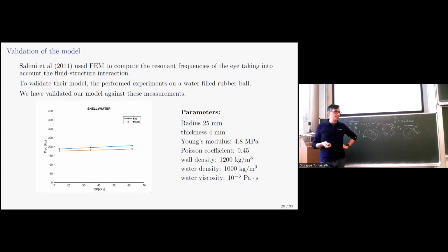And the reason for this discrepancy, I think, is because the Young modulus of rubber depends, in fact, on the pre-stretch. So if you change the pre-stretch, the tangential modulus will change, and this will result in an increase of the vibration frequency. You cannot do this using a constant Young modulus. A constant Young modulus will not work on a spectrum of frequencies, because if you increase the stretch, you will have a different stiffness of the material. And in fact, this is quite relevant for the mechanics of the eye as well. But of course, this was just to check that what we were doing was fine.